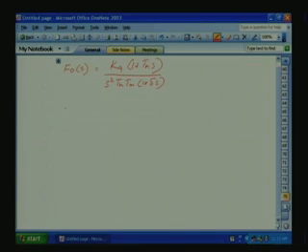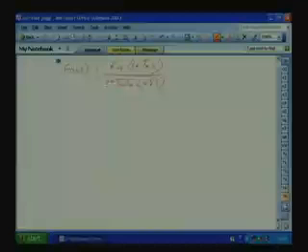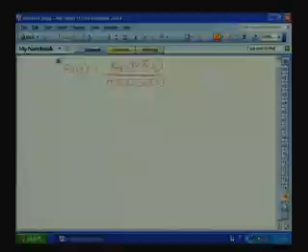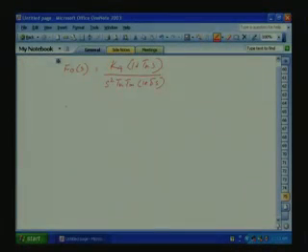Now, from control system theory, we know that one condition for stability is that the loop gain of the system should cross the unity gain with minus 20 dB per decade. So, let us draw the frequency gain of this.